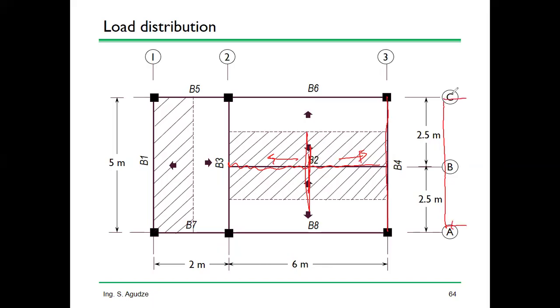And remember that this one, we divided, and this going here. So this beam is only left hanging here, only a beam. There's no slab here, isn't it? Then this load here will be placed as a point load. So the only thing we'll do is the beam self-weight, which is on this. Then you are through. Okay? So it's not a difficult task.